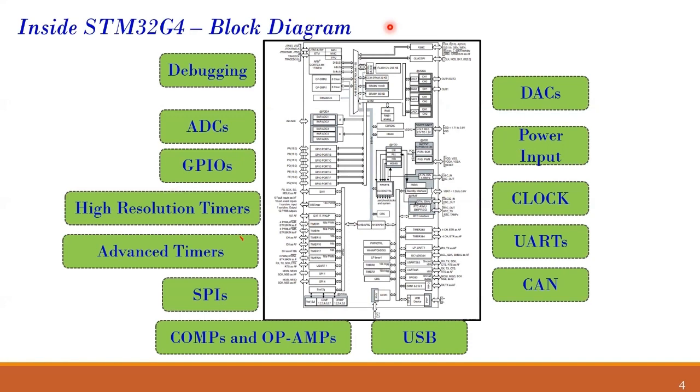You can see you have the ADC over here, you have timers over here. Various features are available for you to use, and you just have to power on the microcontroller and dump a code. On the Nucleo board, there's a debugger which facilitates dumping the code from the computer into the microcontroller, and then the microcontroller has the code and it can run.